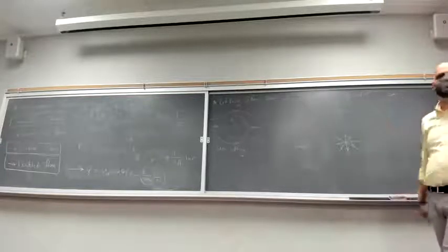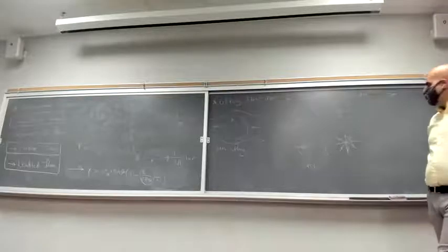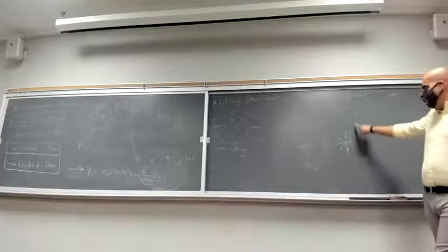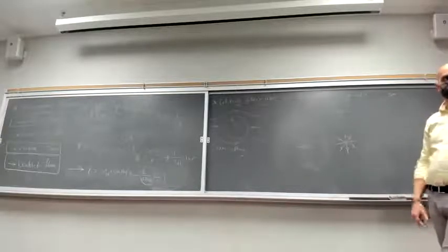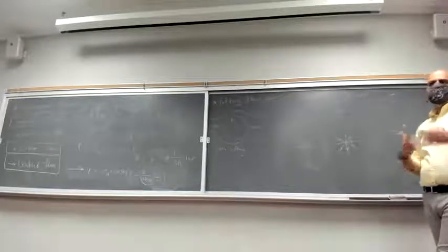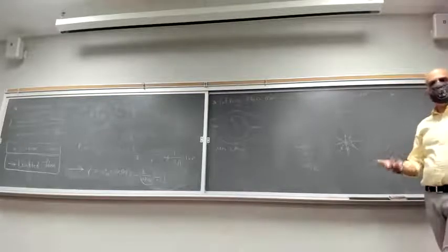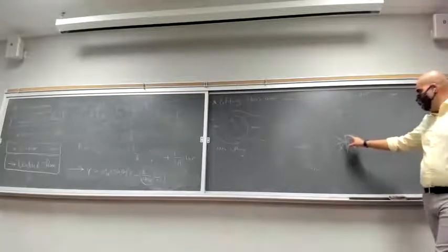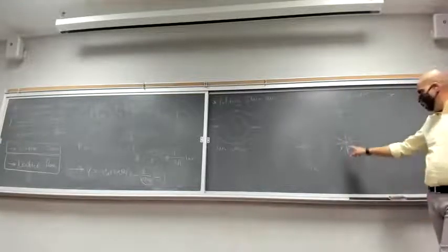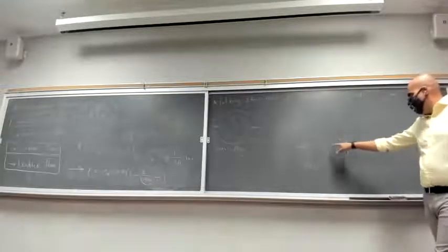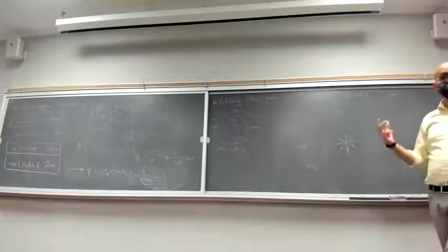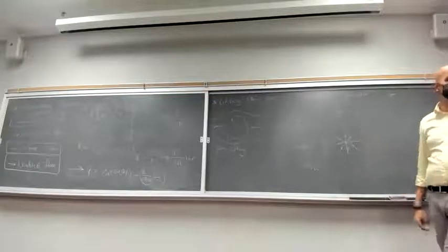Someone from these first two rows, what do you think? What do you think will happen if we combine these two flows? You just have to be able to visualize it and add the vectors. Some vectors are in the opposite direction, so they will cancel each other out. You will get a stagnation point somewhere. And the idea of the source flow was that the strength becomes smaller and smaller as you go forward. So you have the highest velocity here, and then as it diffuses, the velocity becomes lower and lower. So what would you expect to see if you just combine these two flows?